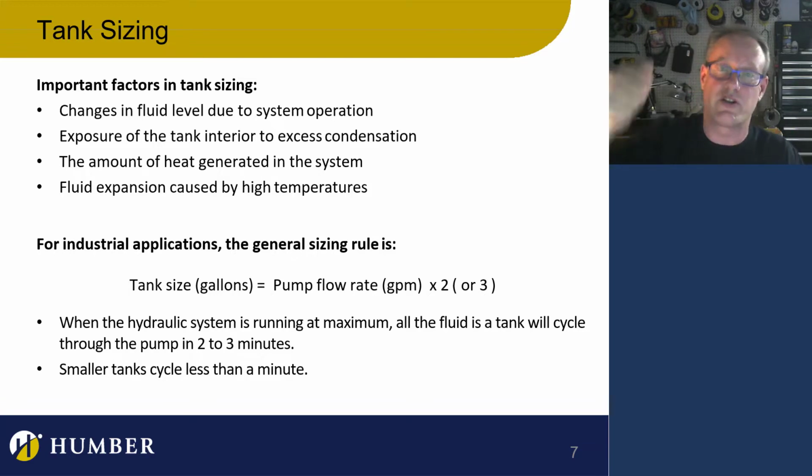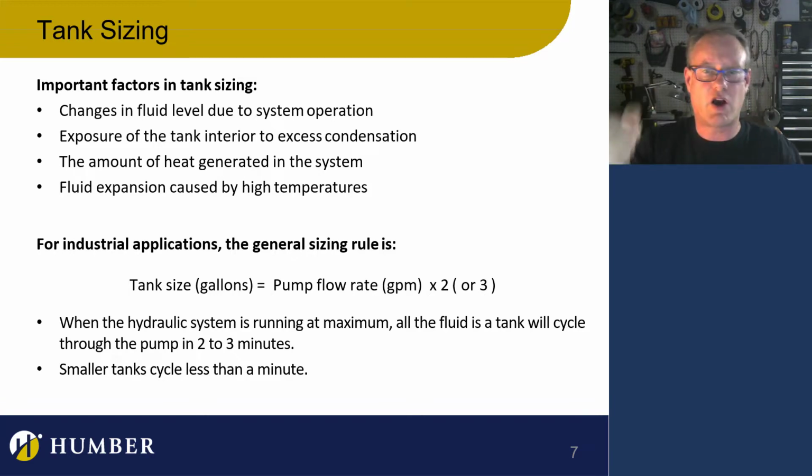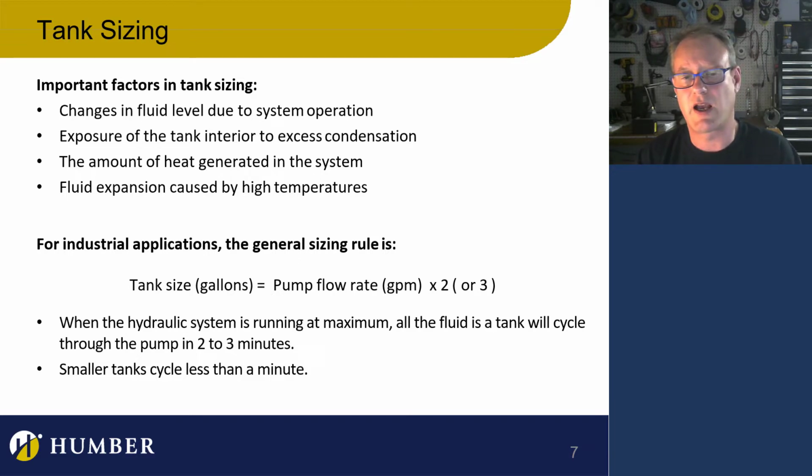If you were to constantly steer, all of the fluid in that tiny tank would be used within 20, 30 seconds. So sometimes the tank is a little bit smaller, but typically we want to make sure the tank is at least 2 up to 3 times larger than the maximum flow rate required for your system.